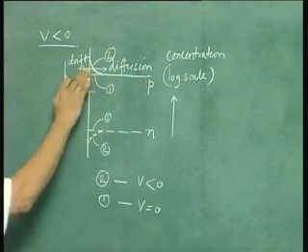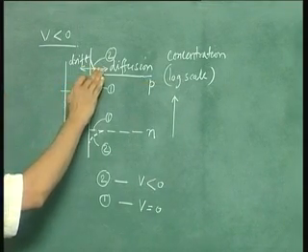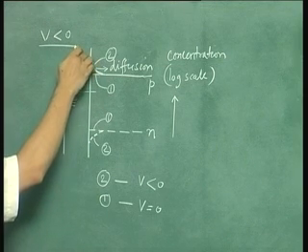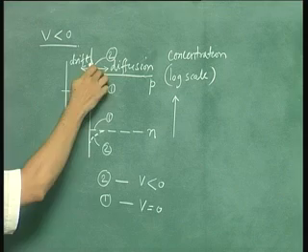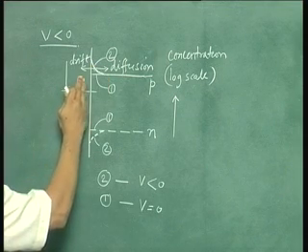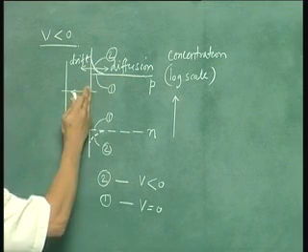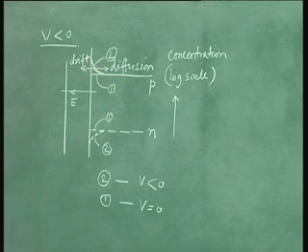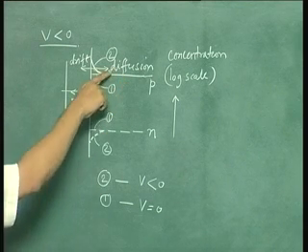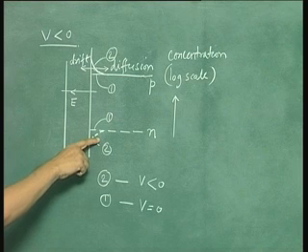So they are exactly in balance, okay? So that under steady state conditions you have a shape like this. At each point the drift and diffusion would be in balance. As you move away from the interface, the effect of the field will not be felt, and therefore you have a flat concentration. You can similarly argue for the electrons. I leave it to you as an exercise.